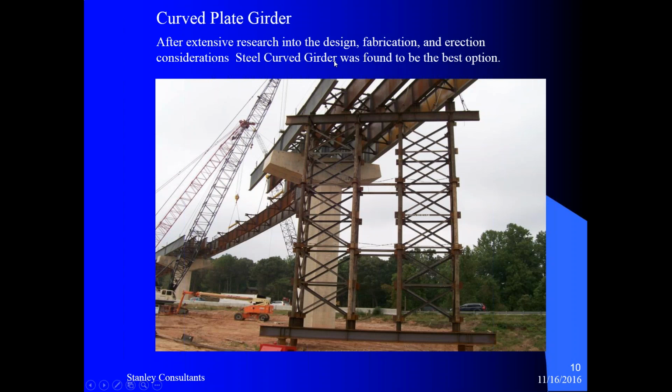After extensive research into design, fabrication, and erection considerations, the steel curved girder was found to be the best option. Here's a picture of a plate girder being erected. Some shoring is required because these girders, due to curvature, tend to tip over.